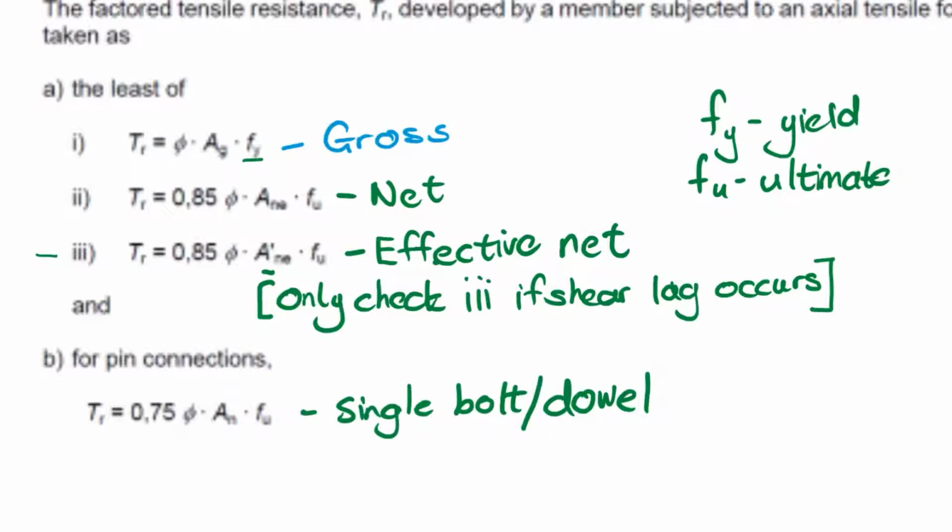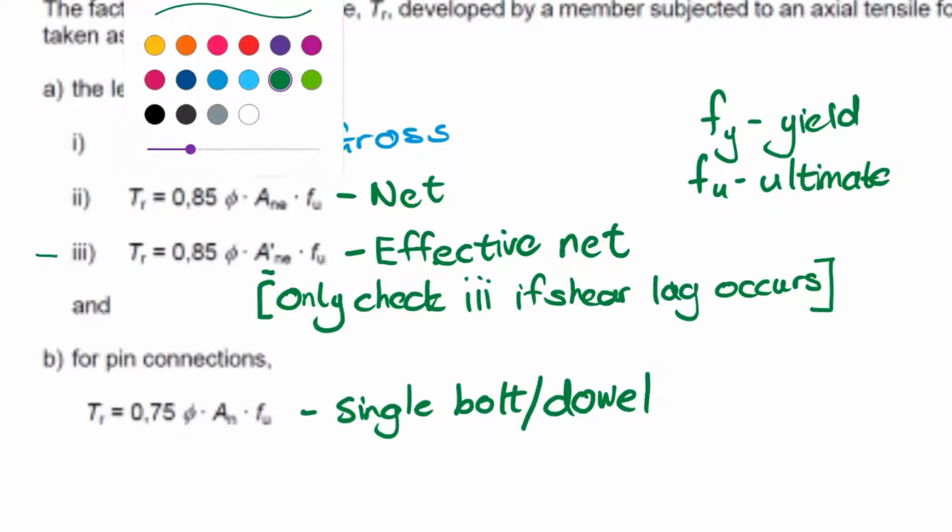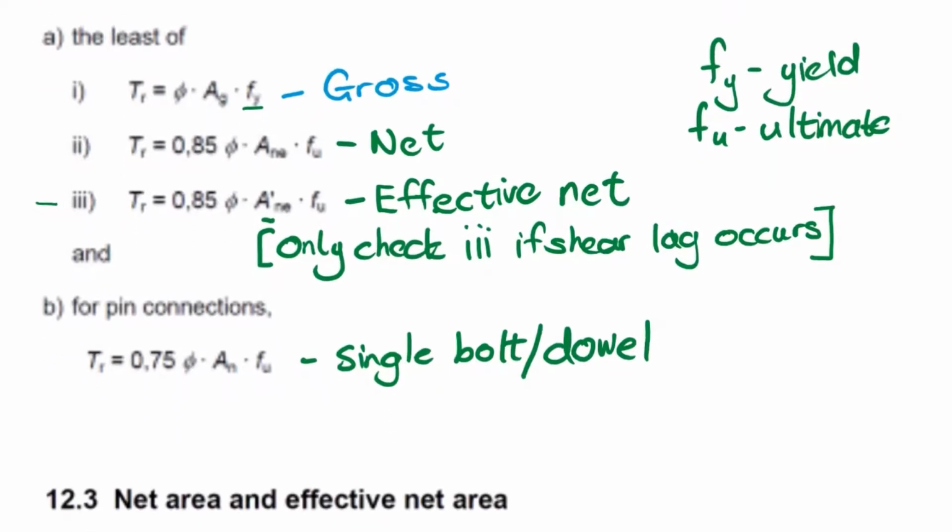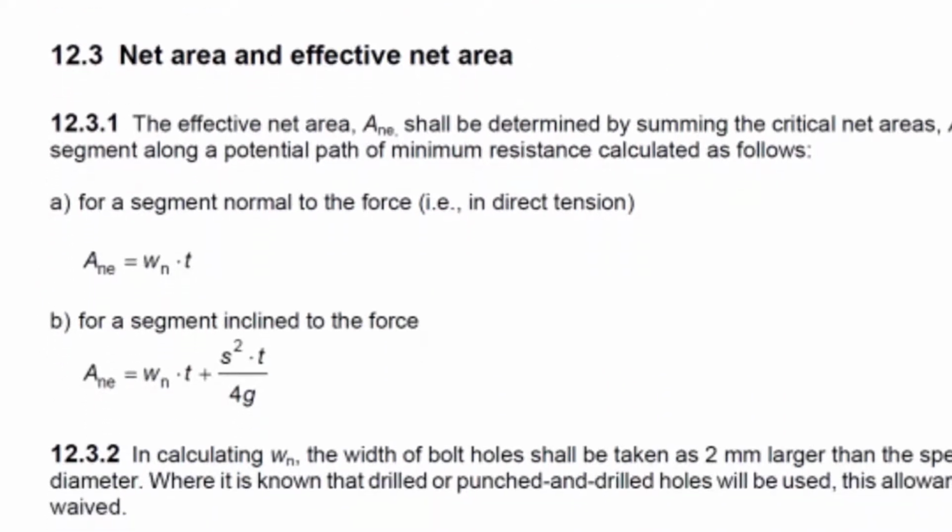It was quite a bit stronger than the supplier said, and it was loaded, and it got to a point it yielded, especially this thinner section in the middle. At that point it would have started elongating, and then soon after that it got to fracture. And this is actually the ultimate strength that it got there, and then it necked and it broke, and we ended up with a failed section. So that's just looking back at ultimate stress and the yield stress, where ultimate is also your fracture stress.